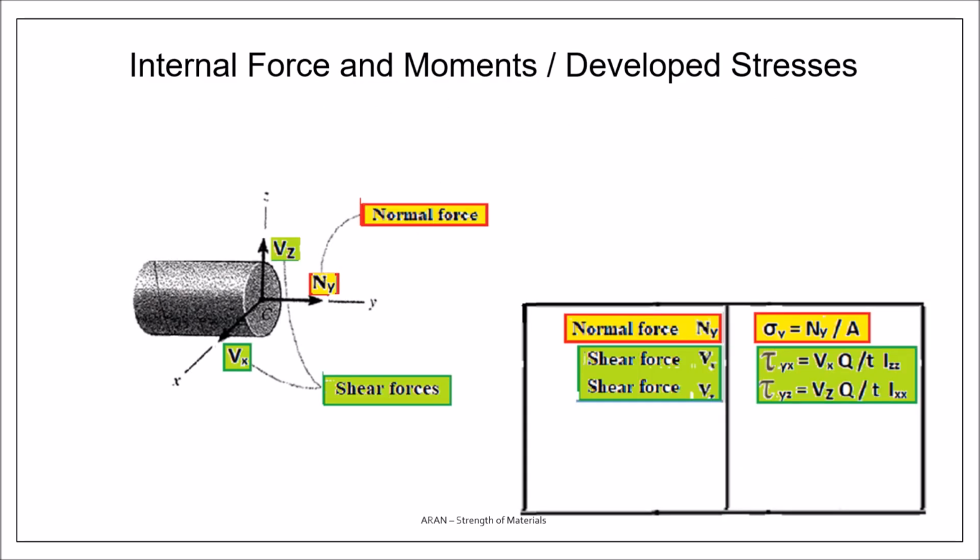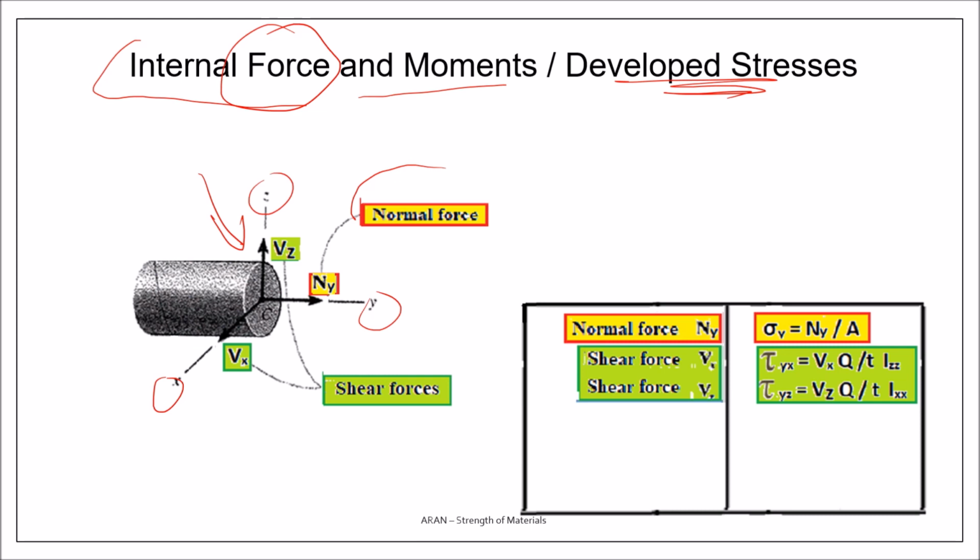Well, let's take a section, and in this section, let's put all internal forces and moments and try to find the developed stresses. Let's start with the forces. What type of forces can be effective? Well, if X, Y, and Z are my coordinate axes, the first is the normal force.